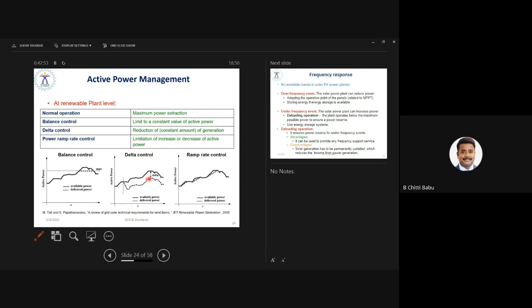Sometimes, according to the changes in the demand, the load power and available power follow the same response. This is what is called the delta control. It means reduction of power generation if the load demand reduces. But mostly we don't go with the delta control, reducing the supply as the demand falls. Sometimes, if the load demand reduces, the surplus power may be stored with the help of an energy storage device, so that it may be used when the demand is more than the supply.